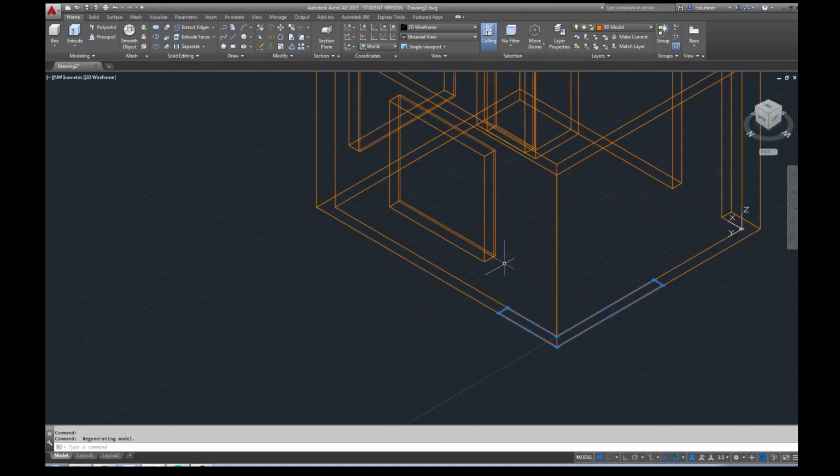And that object, for example, I can simply move up. For example, here. And then say 2 feet, the move tool. Then I can extrude it. Spacebar, snap to this upper edge point, click.